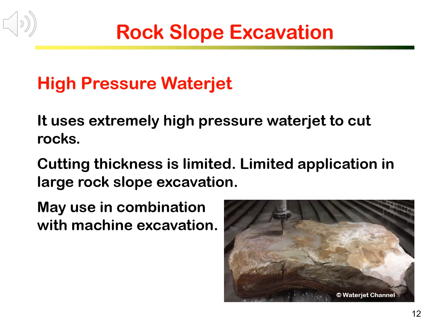High-pressure water jet has been used to cut and carve rocks. The basic principle is to use extremely high pressure of a thin water jet. The high pressure thin water acts like a sharp drill to penetrate and cut the rock. The cutting is very precise, and this is why the technique is used mostly for dimension stones and carving letters and figures on rocks.